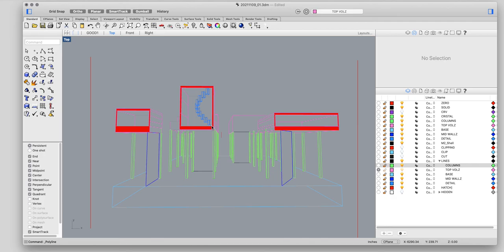Okay, so try doing a MAKE2D with your model and then adding in some hatch where you added the thicknesses before, and then find where the vanishing point is using the lines that MAKE2D has created, and see if you can add some more detail right here in Rhino.